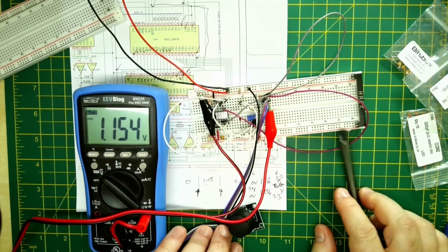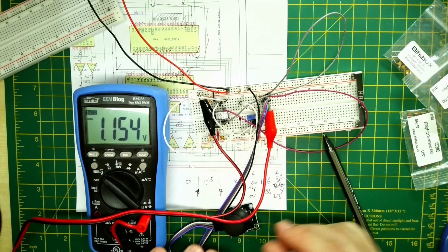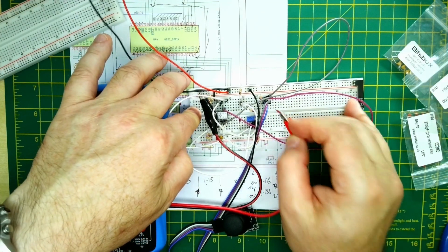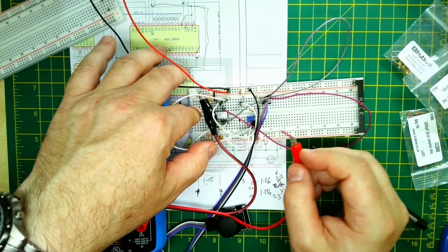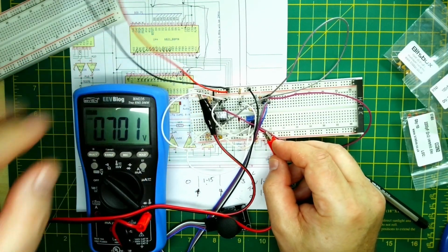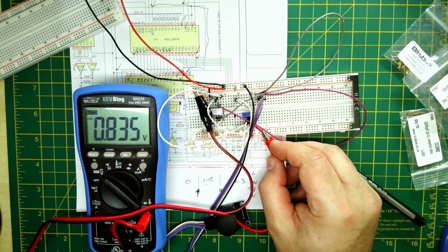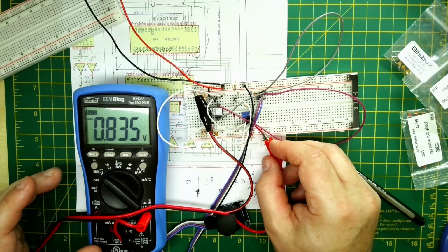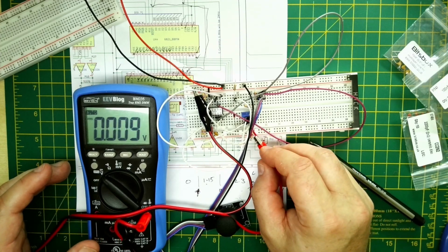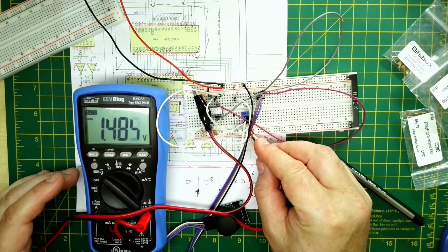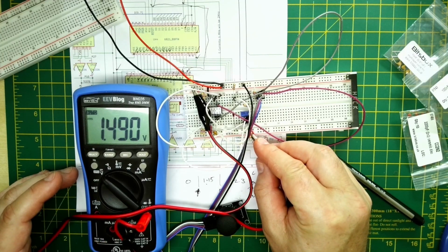Okay, so that's just showing the range that we're getting there. So now if I check the voltages, this is the low reference voltage, about 0.8 of a volt. If anything goes below 0.8 of a volt, then it will be considered low. And if we look at the other line, this is the higher voltage, a high reference voltage of about 1.48.